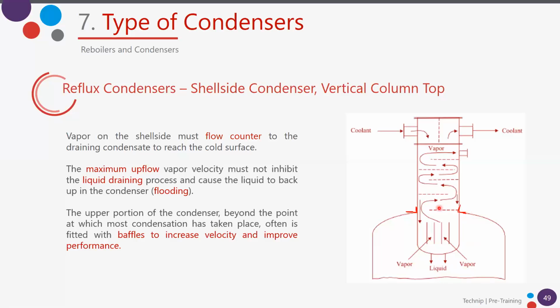Yes, the main use of the baffles in this exchanger, but also in all exchangers, no matter if they are vertical or horizontal, is to force the liquid to pass through the tube bundle. Since they are forcing the liquid or vapor, they increase the velocity.